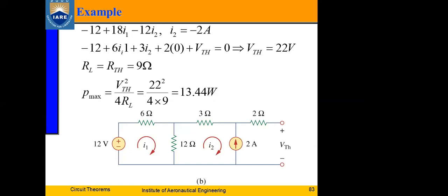Now, how can you take the ammeter here? As I said before, you will not have the ammeter directly here. Instead, you have a current measurement. Go to the measurement library and take the current measurement. You can observe a plus sign, a minus sign, and the I symbol with an arrow. Now this arrow you have to connect with the display. So go to library.